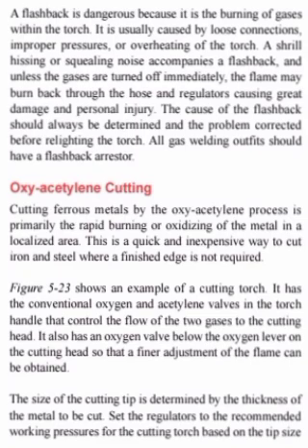A shrill hissing or squealing noise accompanies a flashback, and unless the gases are turned off immediately, the flame may burn back through the hose and regulators, causing great damage and personal injury. The cause of the flashback should always be determined and the problem corrected before relighting the torch. All gas welding outfits should have a flashback arrestor.